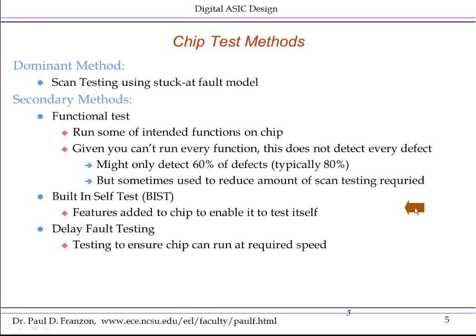It is sometimes used in mission-sensitive applications such as aircraft, because quite often in aircraft avionics, particularly mission-critical avionics, you can actually apply these self-test features to test the chip every time it's powered up, and thus self-discover that the part is working or not before you go off and fly into the wide blue yonder with it. Similarly for missiles and other applications like that.